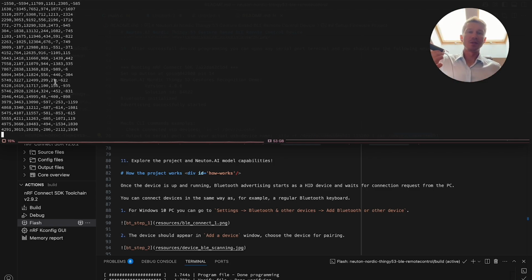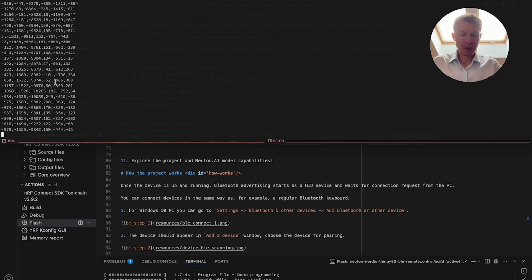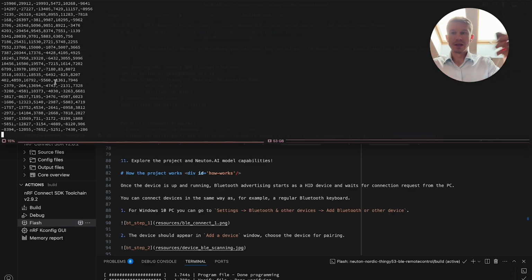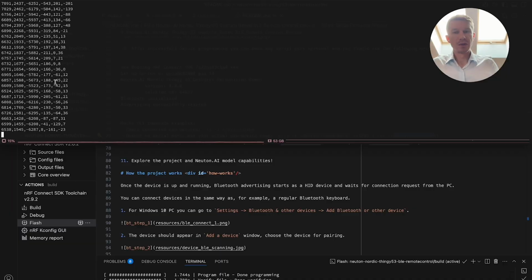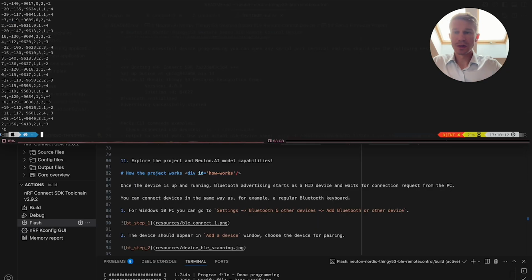As you can see, once I start moving it, you can see the sensor data demonstrate the movement. So yeah, that's how you output the data into the serial port. But now you want to save it, and you want to do this for different gestures. So the way to do this is you run the same command and then T and just the name of the CSV file, gesture one session one CSV. This is how I'm going to call it.